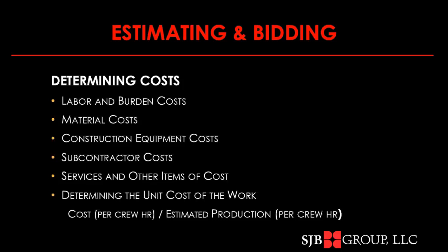Under labor burden and costs, that's a function of how the work's going to be done. What's the scope of the work to be done? Kind of by that, I mean, is it a little bit of digging, which says we're going to use a shovel, or is it a lot of digging to do, which means we're going to use a backhoe? Who's going to be doing the work? What trades are involved? What level of skill are we going to need for the particulars of the work? And then how long is it going to take for the crew to execute this particular work as we're proceeding through our estimate?